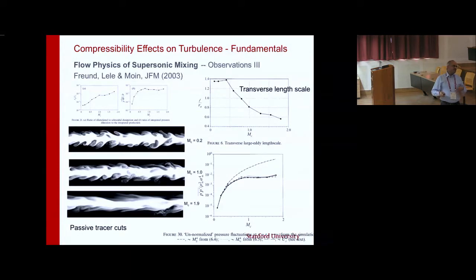So this is not unlike similar phenomena that happen in stratified flow, where the Richardson number, once it is exceeded, there is this layering tendency that happens in stratified flow. Of course, there is no mathematical analogy between this problem and the stratified flow problem. I'm just drawing the analogy in terms of turbulent structure change. What is happening here is that pressure is controlling the action.